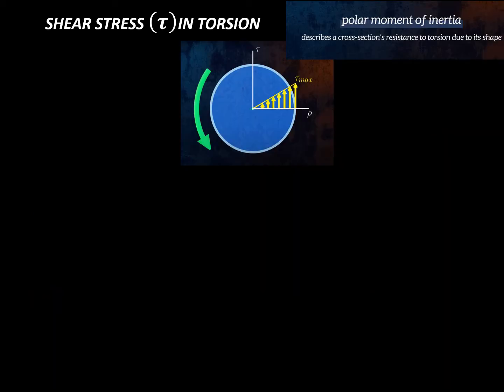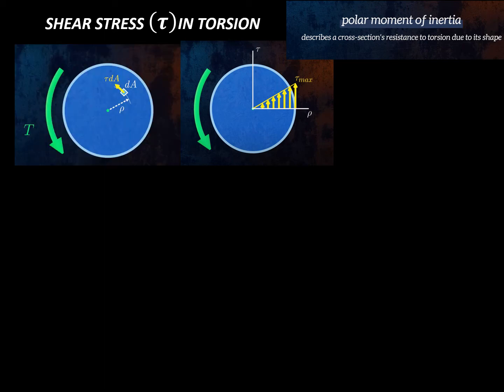We're going to generate an equation to describe how the shear stress is changing within this end-on view of one of these discs. So I already mentioned that this is varying linearly with the distance from the center of the disc. So it's greatest on the edge and 0 in the center. So we can look at one little area within the disc and look at the force that's acting on that. So shear stress, of course, is force divided by area. So it's the little teeny force divided by that little teeny area, so that you can therefore get that little incremental force, which is going to be equal to the shear stress times that area.